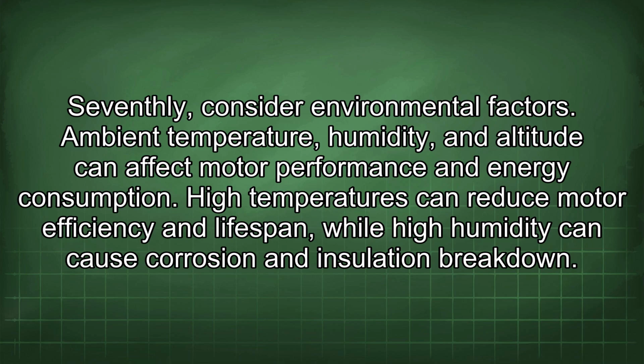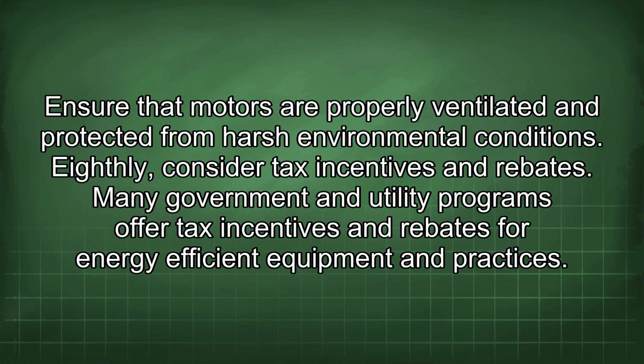Seventhly, consider environmental factors. Ambient temperature, humidity, and altitude can affect motor performance and energy consumption. High temperatures can reduce motor efficiency and lifespan, while high humidity can cause corrosion and insulation breakdown. Ensure that motors are properly ventilated and protected from harsh environmental conditions.